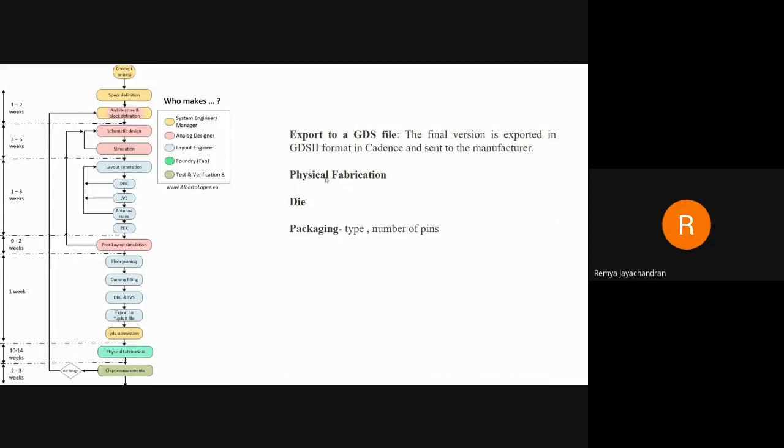It will undergo the lithography process, oxidation, deposition, etching, and all the processes, and you will get the final product, that is the die. And you can measure the parameters from this die. And if it is working, then you can go for the packaging of this die. There you also have to look into which packaging to use, and you have to find the packaging industry for that.